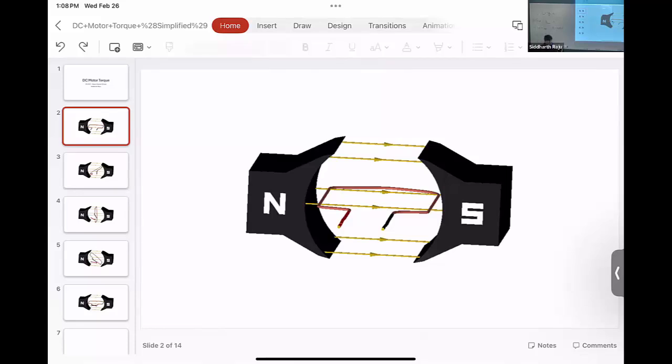Shouldn't there have to be flux lines outside of the magnet as well to make the divergence zero? Yep. So the diagram that I've drawn here is not how it would actually be in a motor, right? This is how all textbooks would like to draw the motor magnets, but we already said there are no magnetic monopoles. So for every north, there should be a south.